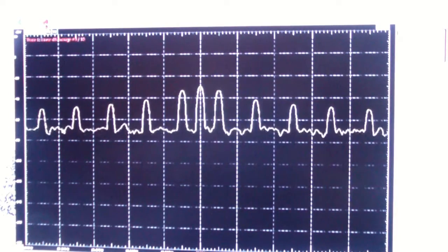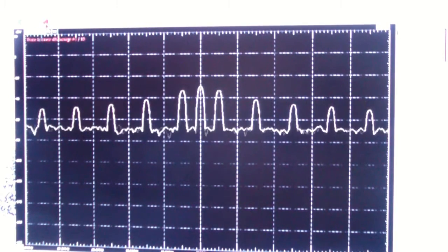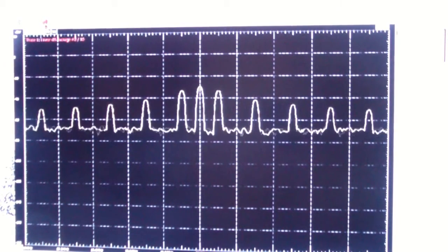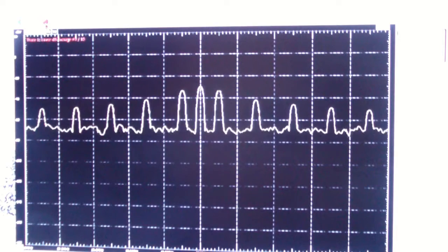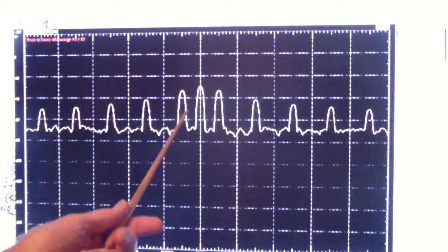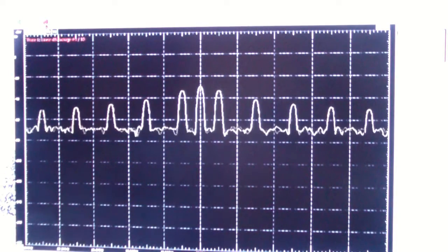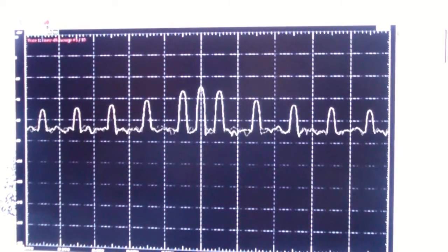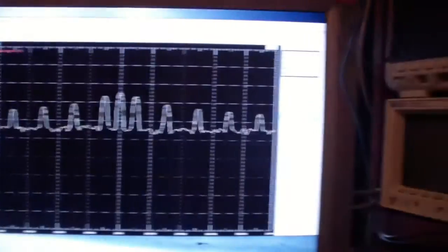The reason that I show you this is I got to working with the Analog Discovery 2 and the spectrum analyzer, and I realized that it has some wonderful properties, and for the money it's a real value. But the one thing that it's limited by is its 50 megahertz bandwidth. Now, by the way, this is just a fast Fourier transform, it's not a true spectrum analyzer. But let me show you what a true spectrum analyzer shows for this same signal.